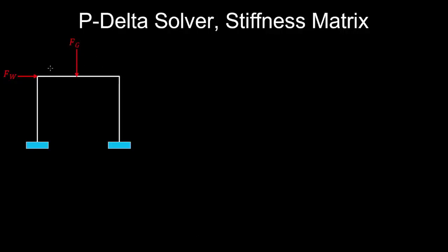Today we'll derive the stiffness matrix for an element that's aligned with the horizontal x-axis in global coordinates. So if we cut this beam element near the ends, we expose internal forces and bending moments. So in our two-dimensional problem, we're going to have displacements in the axial direction at node A and in the lateral direction. And similarly, we have an axial displacement at node B